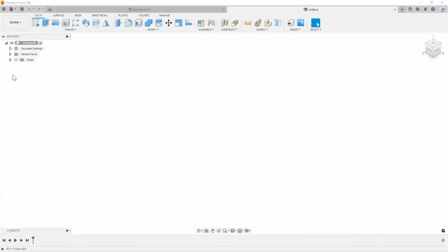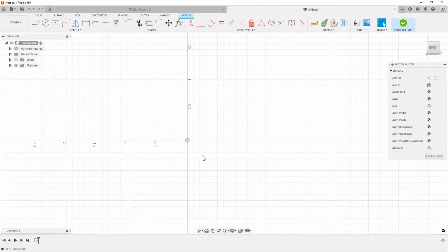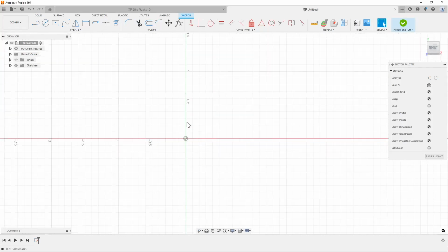Awesome, there we go. Okay, so like I said earlier, I'm going to start drawing right from scratch. Now, I did go ahead and prepare a couple of models also, just because we're on a bit of a time constraint, but let's get started. I'm going to do a simple sketch of this. First things first, I want to create a tube. You can download custom tube models that you can find on the internet, but I can show you fairly simply how fast it is to just draw your own aluminum tubing. So I'm just going to do a quick center rectangle here.